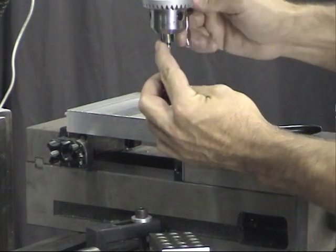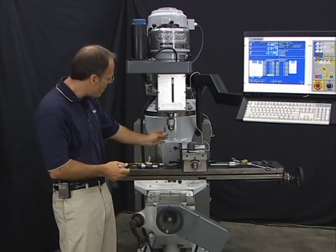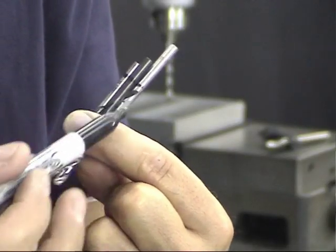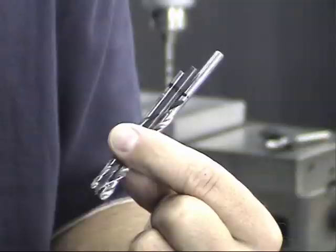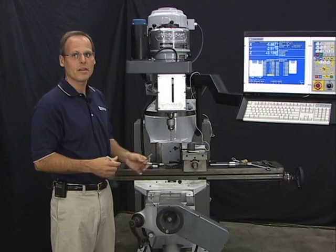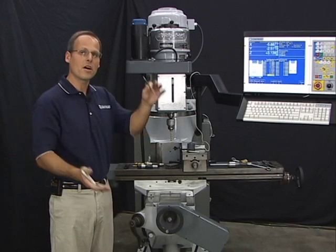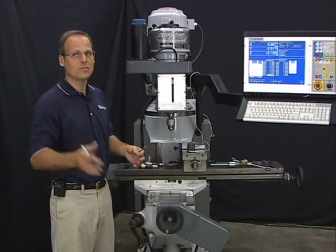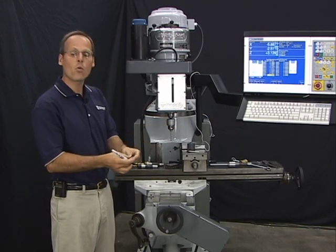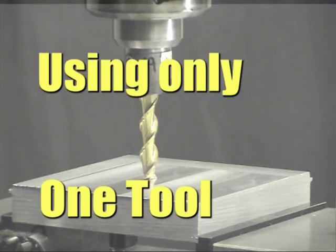And there's a couple different ways to do this. If you're drilling through holes and it's not that critical, you can just use some magic marker, make a mark on there, line the mark up. Yeah, it's within 10 or 20 thousandths, but that's going to be good enough for a through hole. Another method might be putting a collar on the drill bit so that you can repeat more accurately to the same position. That's a quick trick. You might have 2 or 3 drill chucks that do 2 or 3 groups of ranges of different size drill bits. Obviously, I couldn't take a 3/4 inch diameter drill bit and line it up with this 1/8 inch. It's only going to work over a range of drill bits. So that'll save you from having to buy a ton of different drill chucks.